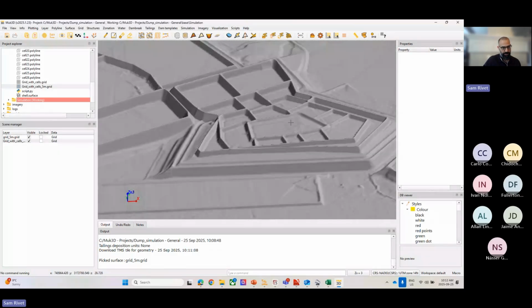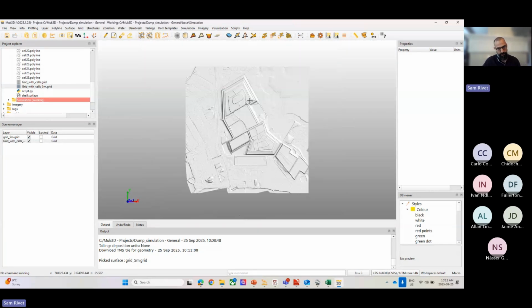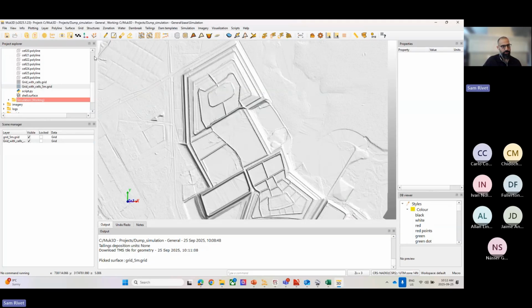So you can see here I added some cells. Just some cell walls using that drawdown function. Just quickly added a bunch of cell walls. And if we want to take a look at it more specifically, I'm just going to quickly make a cut fill map here. Also displaying how easy it is to make a cut fill map.